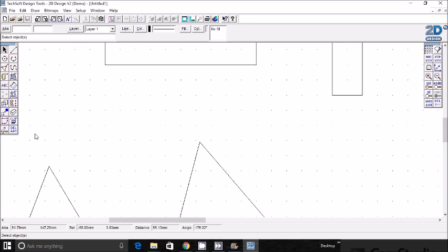Okay. If you wanted to connect those 2 points, let's say with this line, you can use this attach tool. So if I click attach, and then if I go near the top of the triangle and then click, oh, didn't work, press escape. Let me try again. If I click near the top of the triangle, click, see it's gone straight to that point. I go over here and try again, click, you see it's jumped to the point. So there's a way of making sure you stay exactly on the ends of the line using this attach tool.